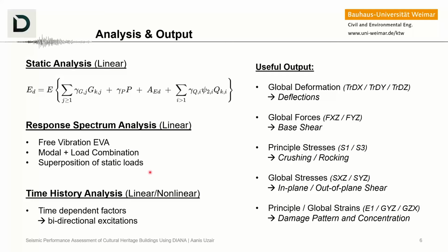Now, some of the useful output that I typically look at when dealing with a preliminary analysis is to look at the global deformations, because they help you understand where most of the deflections in the structural system are. We also look at the global forces, particularly in the nonlinear analysis or a pushover analysis, to determine the base shear forces.